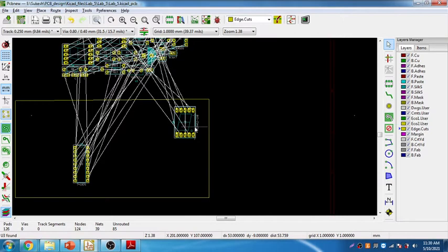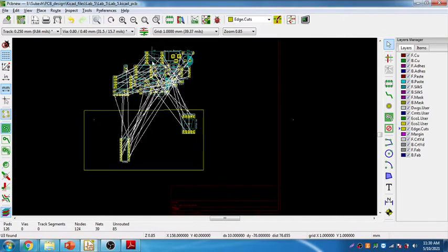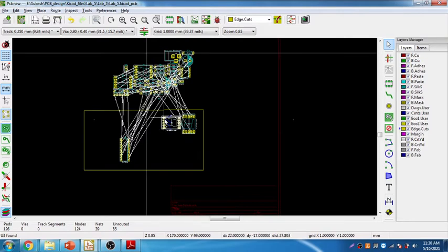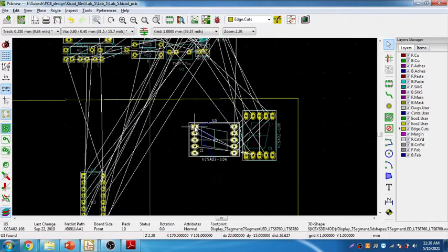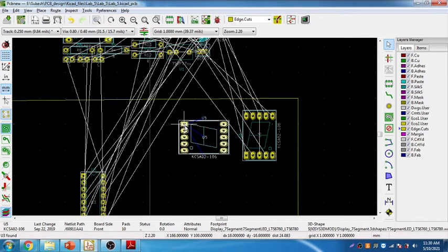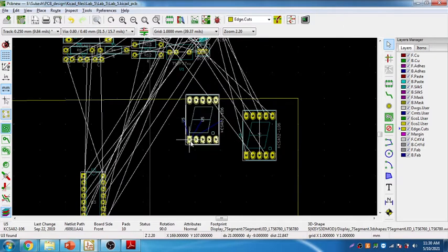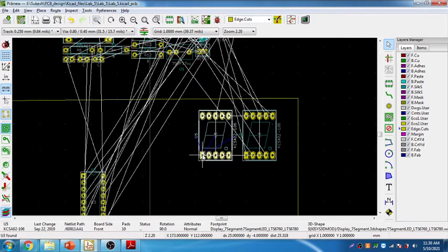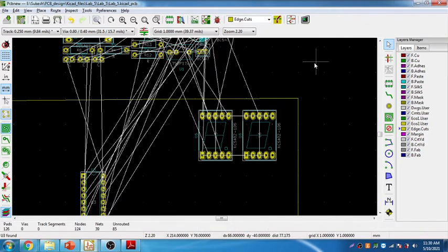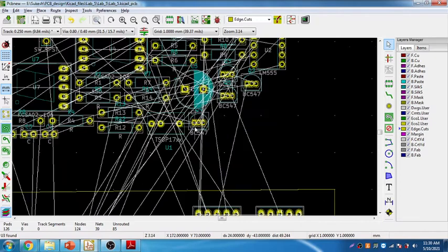And now let's look at the first display, that is maybe this. We'll just see, M to move. That is U5 exactly. Press R, rotate it, place it over here. That looks good. Then next, again zoom in.